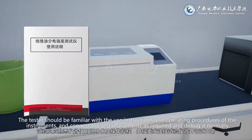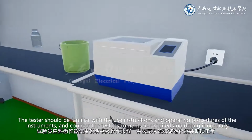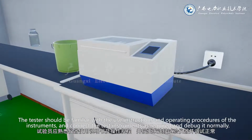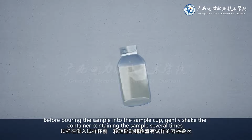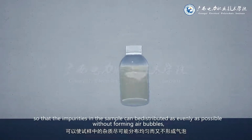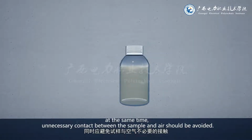The tester should be familiar with the use instructions and operating procedures of the instruments, and connect the test instruments as required and debug them normally. Before pouring the sample into the sample cup, gently shake the container containing the sample several times so that the impurities in the sample can be distributed as evenly as possible without forming air bubbles. At the same time, unnecessary contact between the sample and air should be avoided.